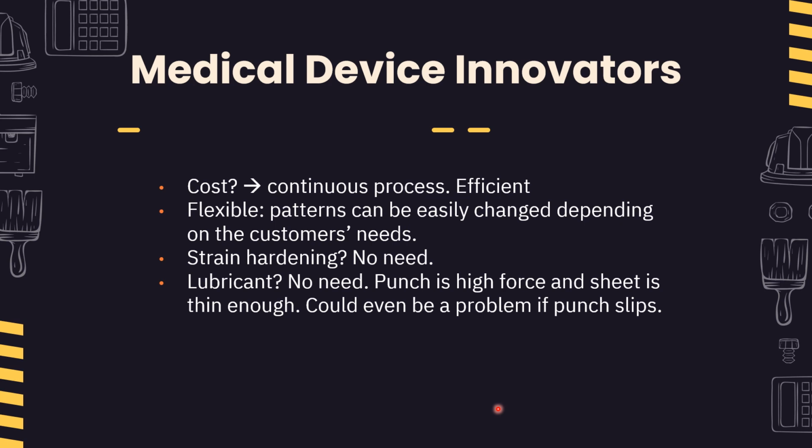So strain hardening, which is usually done for increasing strength and hardness, is not required in this application. We could do it, but it would involve cold working and so reducing the ductility that we had increased previously with hot working.